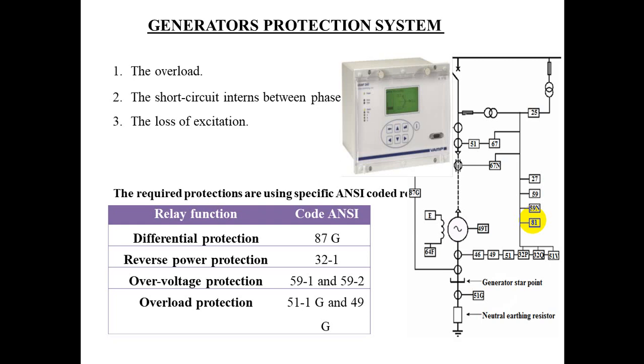Hence, there is no need for grading or discrimination with other earth fault relays in the system. That is why an instantaneous relay is preferable in this case.